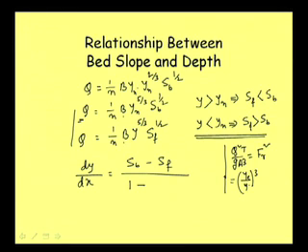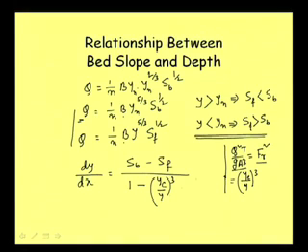We express it like that, and in general we can express it as Froude number squared. Suppose again we can write it as Froude number also, or in this form also. I am writing at this moment (yc by y) whole cube. I will say that this can be expressed by FR squared, and that will also give us the idea whether this part is positive or negative.